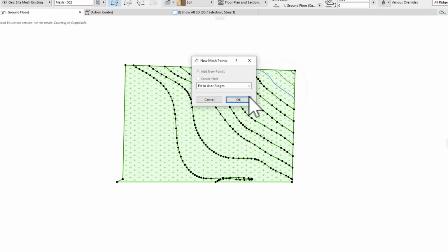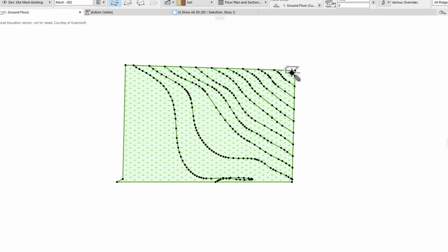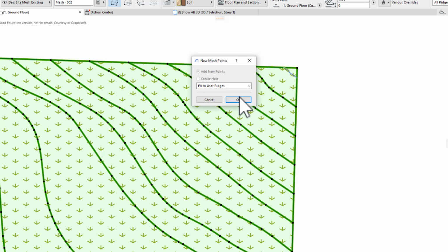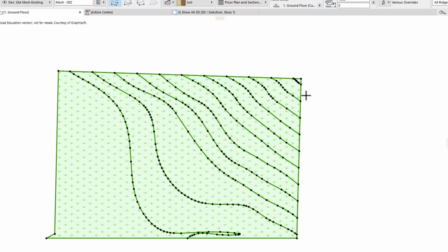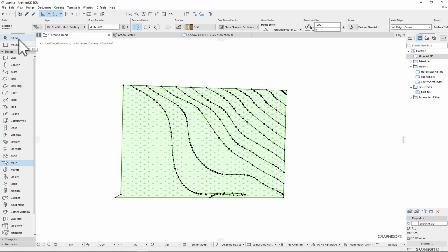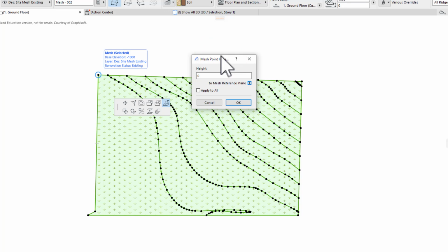Now it's handy to have your Mojo next to you so that you can check the coordinates or the elevations, because I need to, let's zoom in here, make sure I've got that one. So on my Mojo tool, I can go around to the corners and check the elevation of each corner. So I click there. Now if I look at my Mojo tool on my phone, I can see that that spot level is 48 millimeters. So 48 millimeters above this project 0, so I'm going to use that.